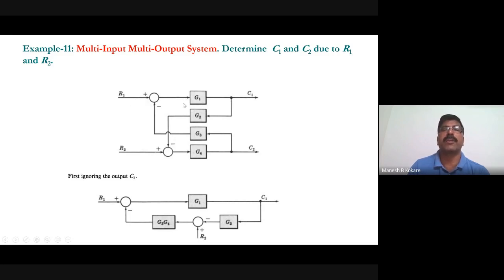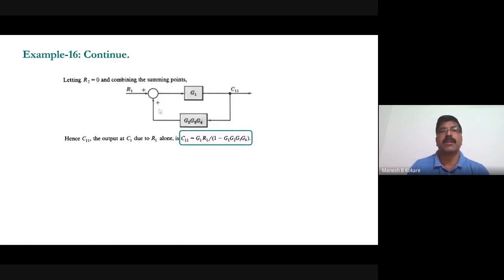This will be eliminated, and then you have to simplify this one. See that when it is 0, this Z1 will be in cascade with this one, and also Z3 is in cascade with this one, and then the whole thing will be basically in loop with Z4, right? So your feedback path gain will be the product of these three, and you have to see the appropriate sign.